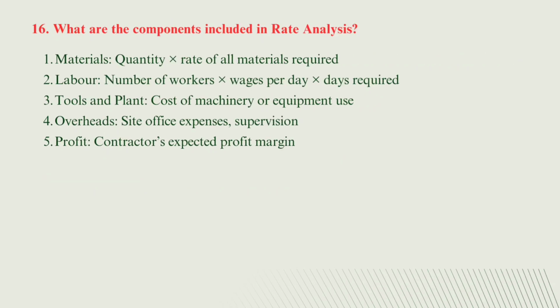The next question is, what are the components included in the rate analysis? The answer is, many components are included in the rate analysis, like material charges, labor charges, tools and plants, then overhead charges and profit. Material cost is equal to quantity into rate of all material required.